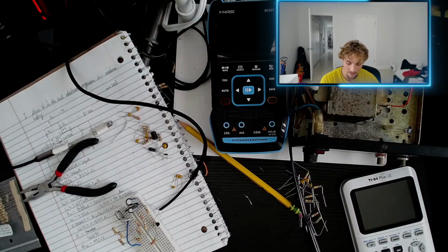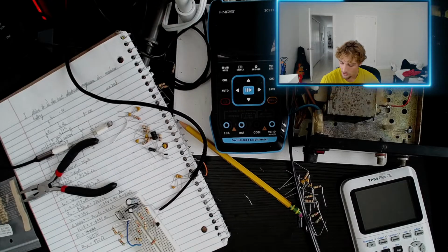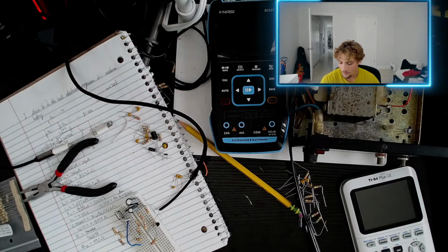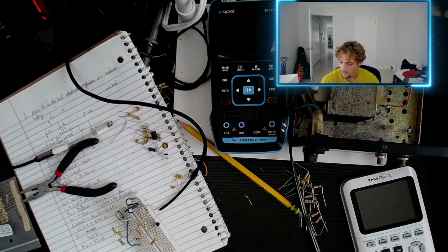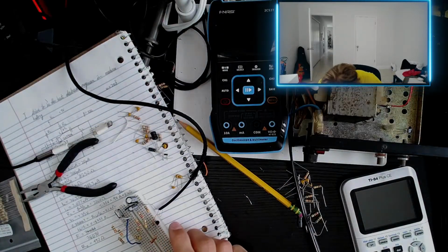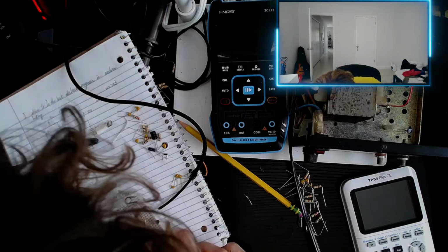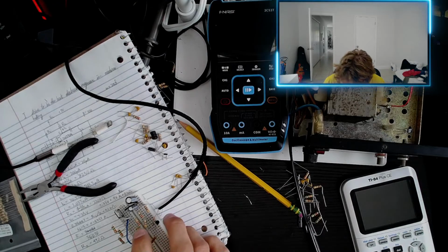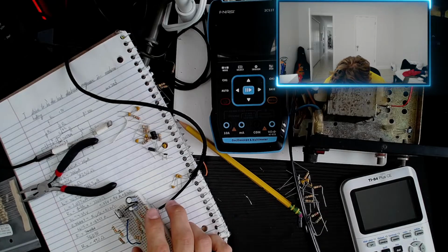So we can go ahead and, before I hook up my phone and then hook up my oscilloscope to record the signal, let's check our bias points. Let's do some measurements for voltage and perhaps current too, although I have too many resistors here, and to measure the current I'm going to have to make a disconnect, and I don't really want to do that. So maybe we'll just do some voltages. Okay. Let me make sure everything is connected properly. Double check connections. Measure twice, cut once. That's all connected.